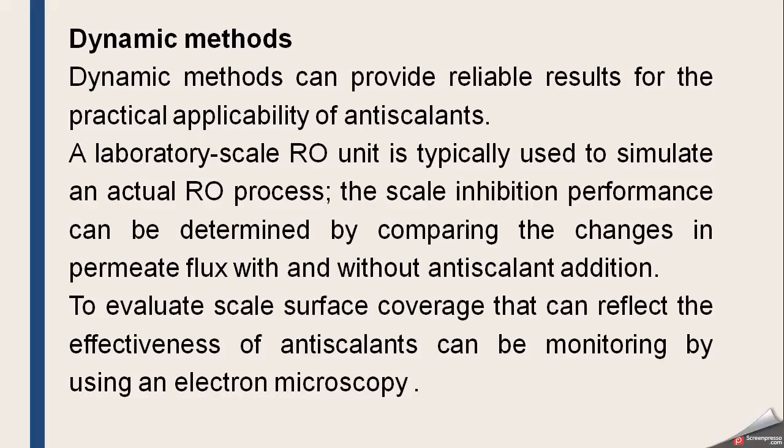To evaluate scale surface coverage, which can reflect the effectiveness of antiscalants, electron microscopy can be used for monitoring. When we use the antiscalant, we will check the surface. When we do not use the antiscalant, we will check the surface with the electron microscope and see how much scale is formed on the surface.